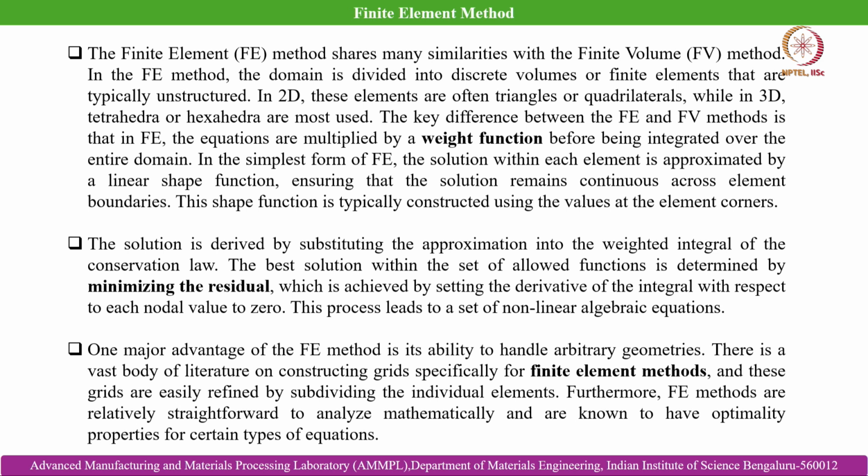Another thing is that in most solid mechanics deformation problems, the elements also get deformed with the body. When it undergoes deformation, it undergoes shape change. So, the domain does not remain fixed, the domain also evolves with the applied load or the deformation conditions. So, it is easier in finite element to subdivide the elements, which is also called remeshing.